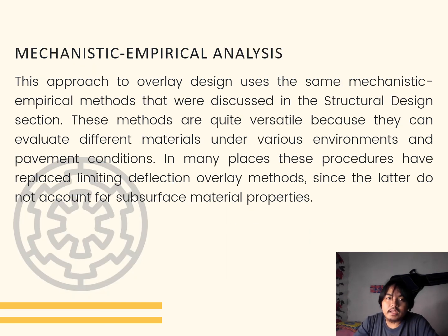Last is mechanistic-empirical analysis. This approach to overlay design uses the same mechanistic-empirical methods that were used in the structural design section. These methods are quite versatile because they can evaluate different materials under various environmental and pavement conditions. In many places, these procedures have replaced limiting deflection overlay methods since the latter do not account for surface material properties.